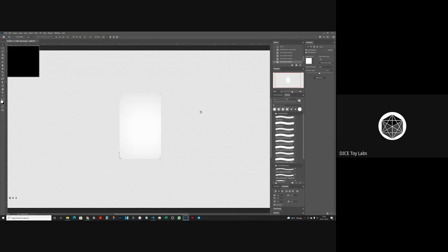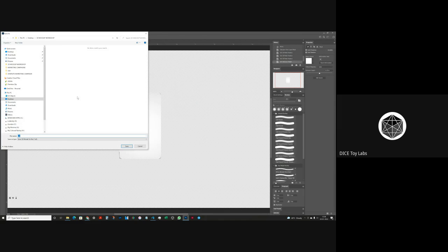Okay. And once you set the extrusion depth to 0.25 inch or whatever it is, you can say 3D, export 3D layer. Here you have to choose STL. None of the other things work. You'll have to choose STL and then export it. So it exports it in the exact dimension that we just created also. Even if it doesn't, we can resize it. That's the best part about it. So let me just call it